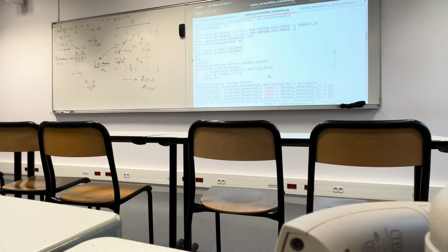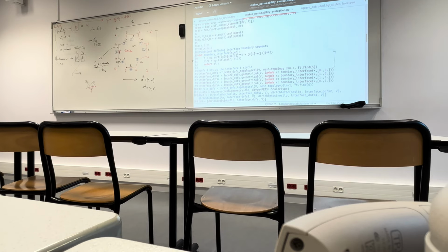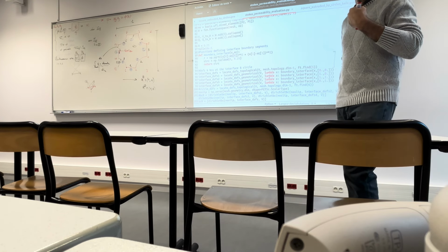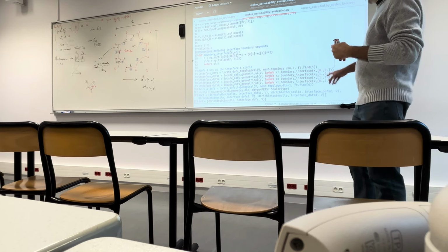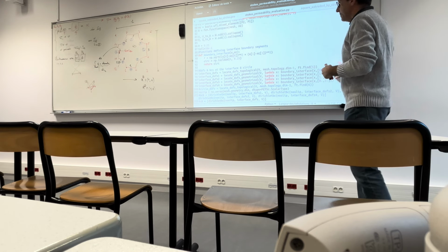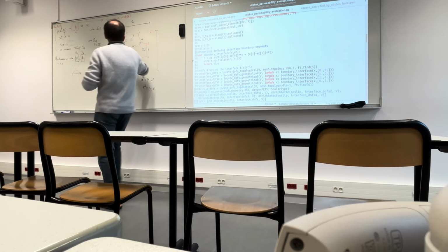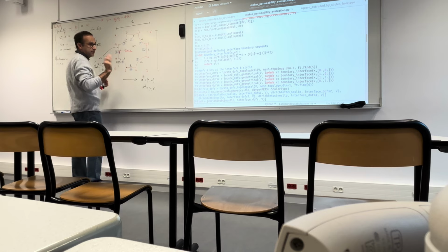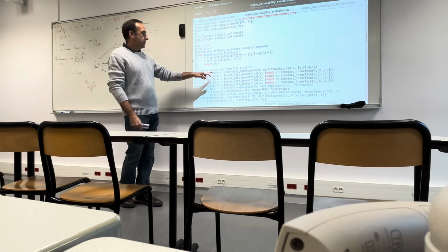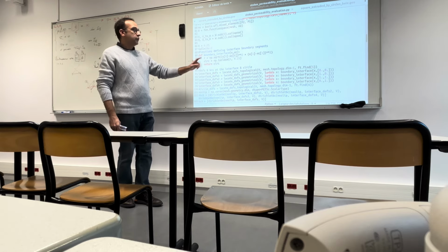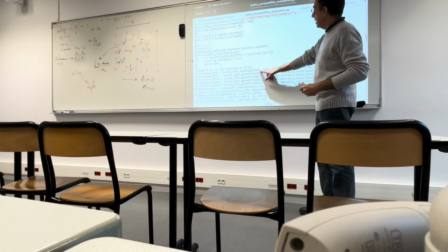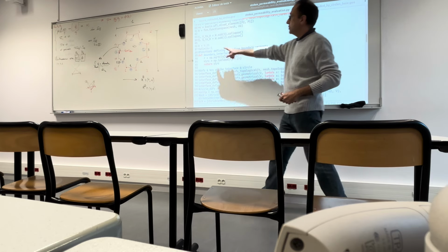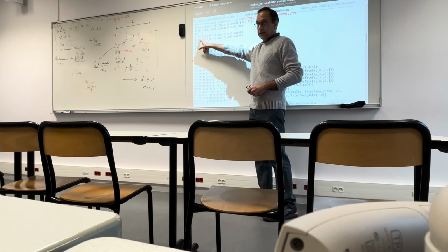So this topological location refers to the labels that we have introduced in GMSH. So if you remember, we labeled with 5 this part of the boundary. So essentially I'm saying call interface degrees of freedom, those relative to velocity, and this is because I'm referring to the space V, which is the space of velocity.